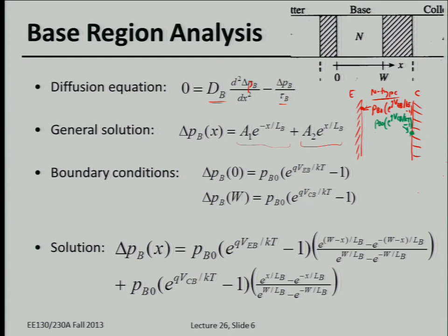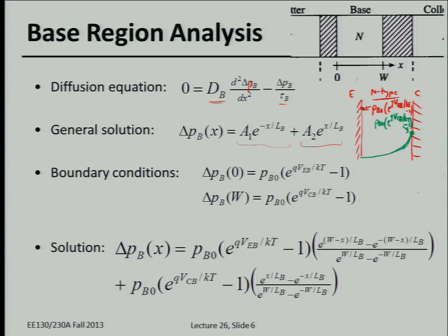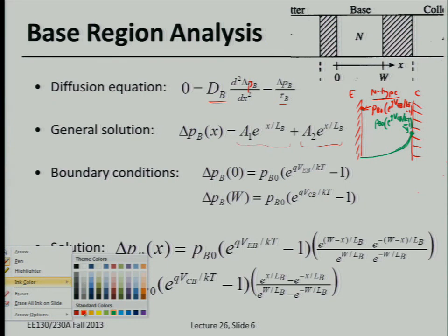So let me just sketch here. So let's say both junctions are slightly forward biased. If this is a long base region, then you expect the excess carrier concentration injected from the collector to die out to 0 over distance. And for the carriers injected from the emitter, you also expect those to die out with the same exact diffusion length, right?